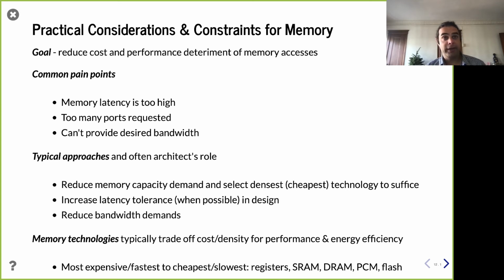Architecturally, like I said, try and figure out ways to tolerate that latency. That way you're not just idling the entire time waiting for memory. If you go through the entire effort of building a specialized hardware accelerator, and it turns out that most of the time it's just sitting there idle because it's waiting on memory latency, well, what was the point, right? And then finally, you can figure out a way to perhaps reuse your data better. You can also perhaps reduce your bandwidth demand, right? Which once again lets you use a cheaper memory and make people happy.